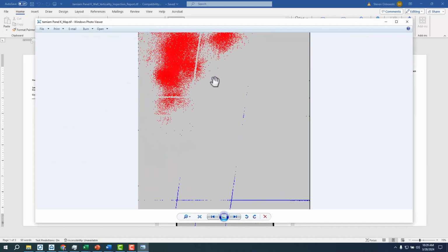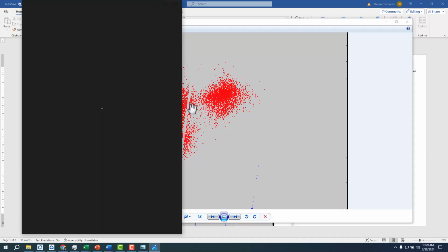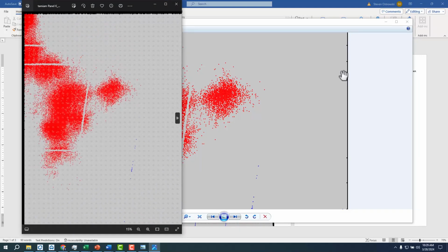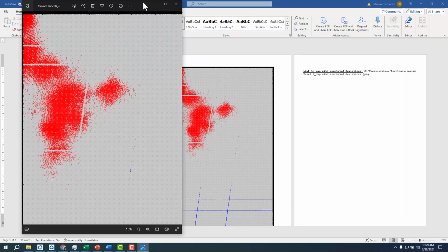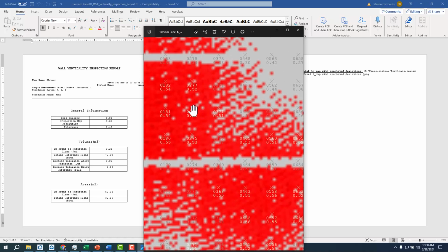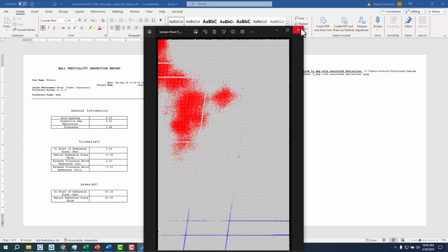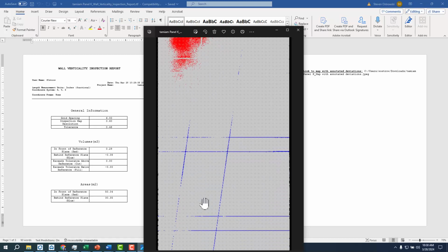And then that image will give me that full report. Another TIFF image where I can start to see the lean in and out of that. I should actually have a nicer one here. Yeah. So here is the TIFF image of that, showing you the deviation from the wall there, where red would indicate it's over 0.5 of an inch or 1/2 inch out, leaning in. So that's pretty good. Actually, this would be leaning towards the scanner, so outside of the building, and the blue is obviously those cut or aesthetic cuts that are inside.